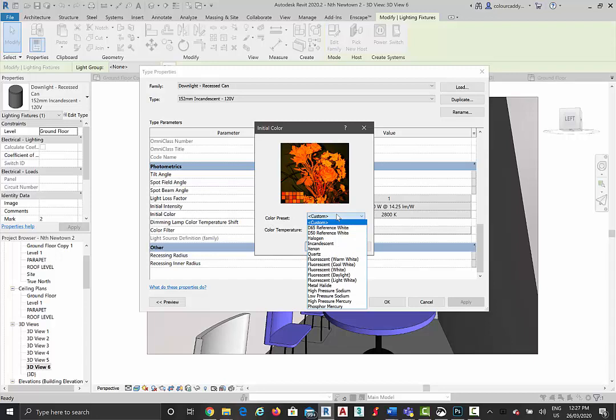So then neutral is between 5,000 and 6,500 roughly. Now you can see with 5,000 it's still a little bit orange, but that still is considered neutral in lighting. And then up to 6,500 and it's almost bluish, if you can see that colour there. It's getting a bit of a blue tinge. But to my eyes, that's almost neutral. But technically that is actually a cool colour when you get to 6,500. So above that, we're getting into the cooler range. It seems strange, but the higher the temperature, the cooler the colour.